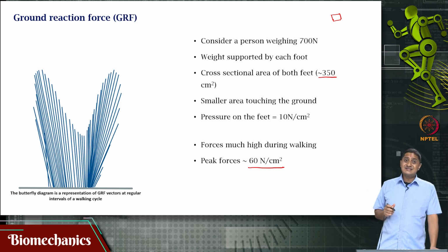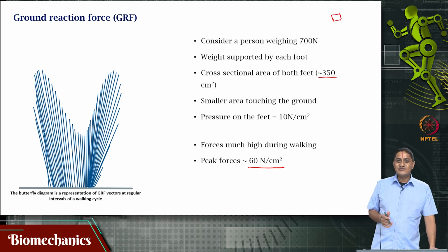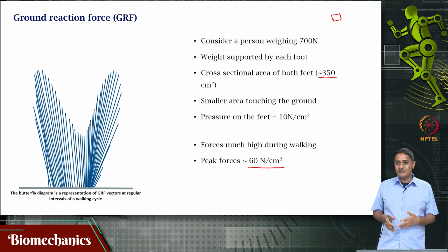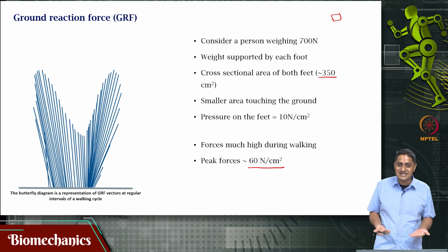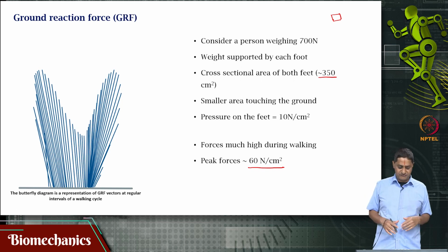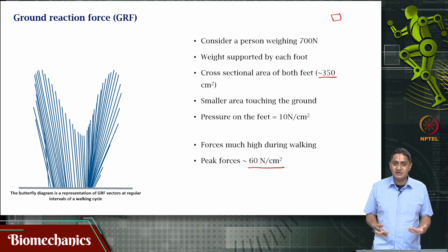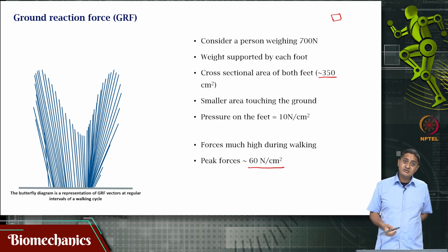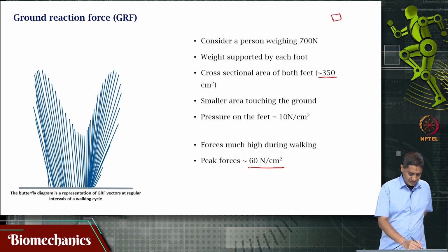And this is not a constant. This varies as a function of the amount of force applied by the feet on the ground. And because the amount of force applied by the feet on the ground changes depending on the phase of walking, depending on the speed of walking, depending on a whole bunch of factors, it turns out that the reaction force supplied by the ground on the feet also changes. Okay. So, this is also something that can be plotted, that ground reaction force is also something that we can plot as a function of the phase of walking, as a function of time. And this is something that keeps varying.